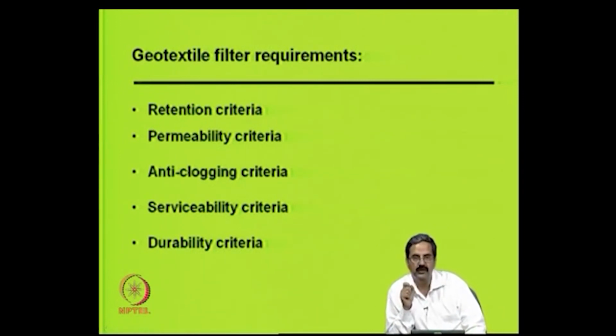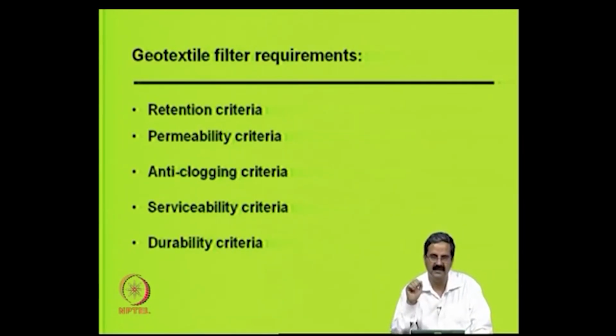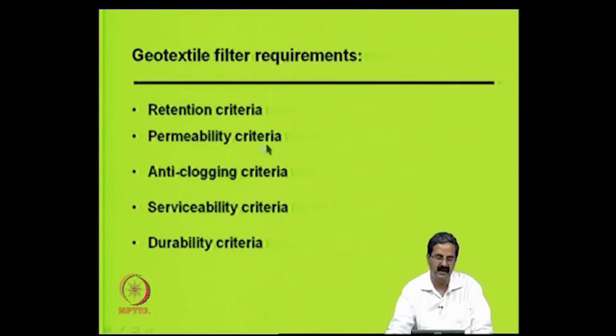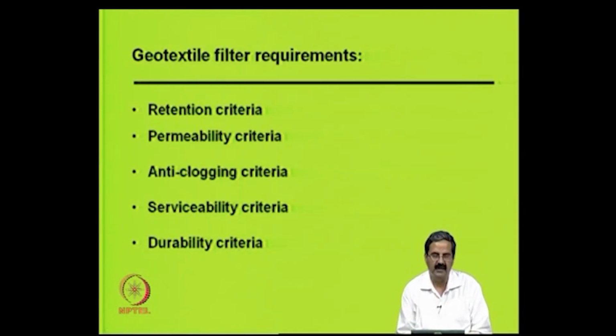So, now we know that geotextile performs better for the simple reason that it removes the water cleanly and thickness is less. We saw the differences between a geotextile filter and a regular filter like an aggregate filter. The difference is good, and if you are putting the geotextile, you should also design it properly. One is retention criteria and permeability criteria and anti-clogging. So, people have thought that Terzaghi's criteria of just soil retention and permeability may not be sufficient.